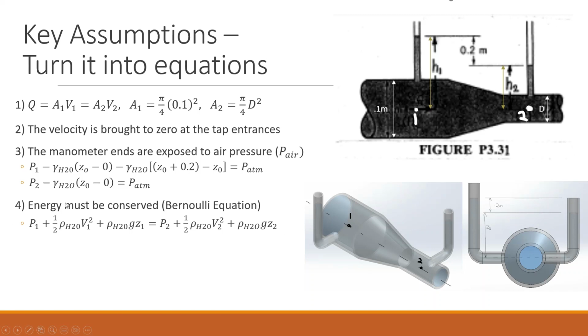Now, some of you may be wondering, hey, wait, I've seen in later classes or later labs that we can modify the Bernoulli equation by adding to this end our head losses due to friction and stuff like that. Why aren't you doing that here? Well, I kind of am. See, these P1 and P2 terms are very loaded. So you can see here in the P1, we actually are going to have an extra term. If I really wanted to, after I threw everything together, you would have a ghost term right here, and that would be your head loss after you go through the choke, right? Anyways, points 1 and 2 are collinear, so these effectively cancel out.